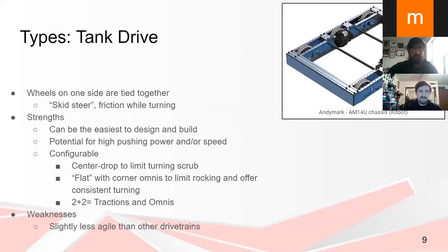So, drivetrain types. There's a ton of different types of drivetrains. The most common one that you will see from anywhere is a tank drive. It's a very simple drivetrain. You can have anywhere between 4 to 8 wheels commonly. I've seen 10 as well, not as often. And commonly one is directly driven from the gearbox, and the rest are powered via belt or chain. There are a ton of different ways to drive it. It is very simple to build, code, and drive.